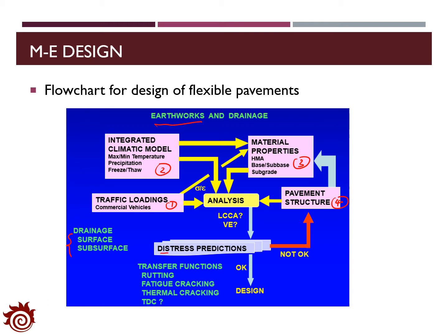If the pavement can provide an appropriate serviceability during the design period, then it's fine for the field construction. Otherwise, we need to go back and modify the pavement structure and repeat the process again until we find an appropriate pavement structure to support the traffic load in the area during the design period.